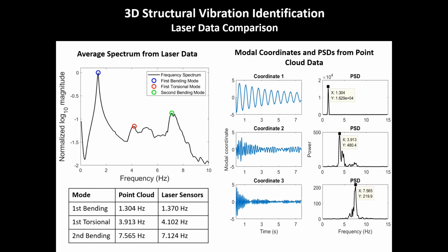For comparison, from the displacement laser data, the modal frequencies of the three estimated modes could be verified using the peak-picking method, with the indication that the frequency values are in good agreement. Only a 0.4 Hz difference regarding the second bending mode stands out and could be tied to the insufficient 3 Hz sampling rate provided by the imager used.